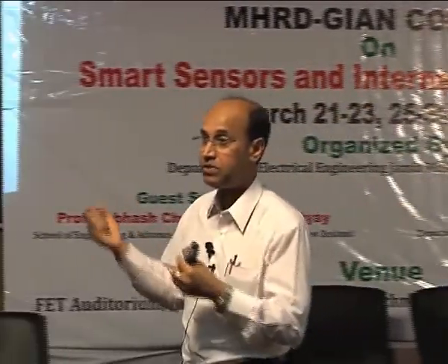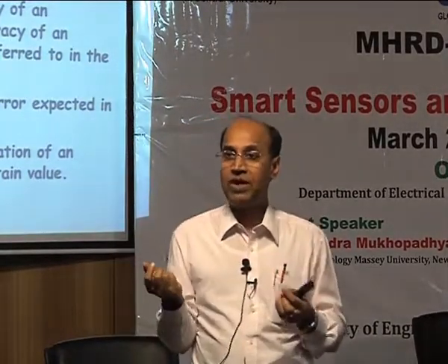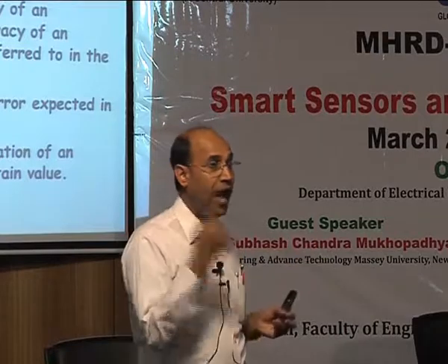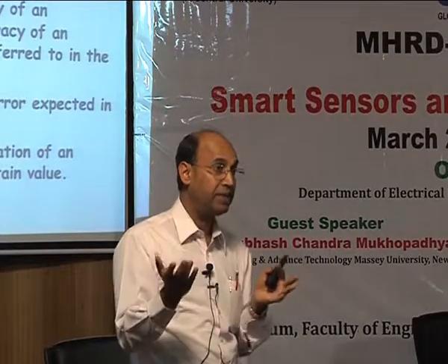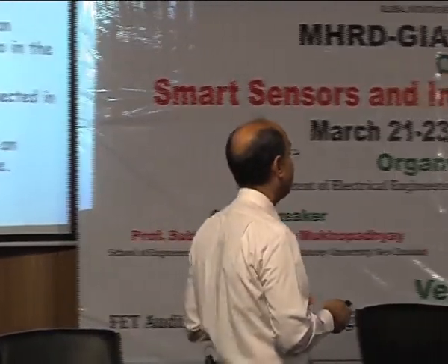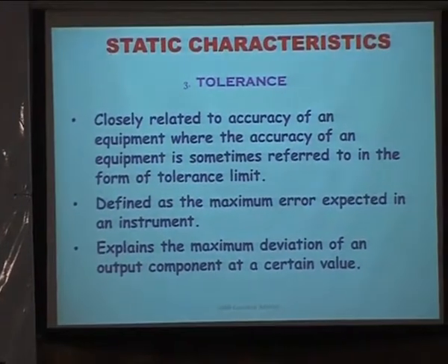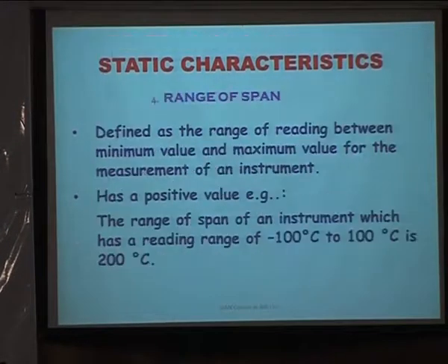Have you heard anyone say, oh, you have got 10% error in your body temperature? No, it's something like 0.1. So in some places, absolute value gives a better representation than the percentage value. So the tolerance comes there. You may have the maximum error defined by the percentage, but when you accept things, it comes to tolerance. So another important thing is the range.